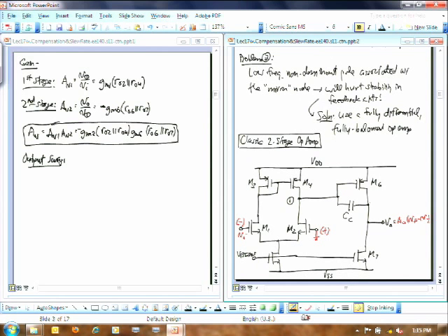It's going to be able to swing, but now look how far it can swing. It doesn't have two stacked devices up here. It doesn't have a current source and an input device and maybe another stacked device there. It's just got one device between it and VDD and one device between it and VSS. So I can very quickly write out my output swing voltage, V output swing.